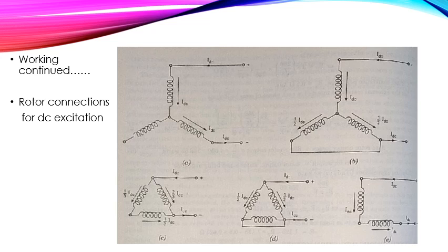So here, due to the current distributions, unbalanced secondary heating is unavoidable with a three-phase secondary, right? But a two-phase arrangement, as shown in figure E, will equalize the heating. However, there is no closed secondary loop apart from that through the exciter, so the damping is not as good as in figure E, right?